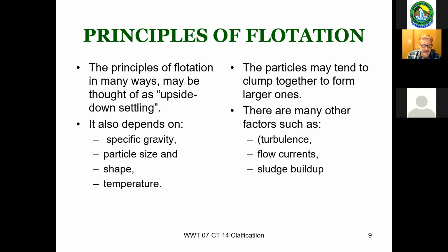Flotation depends on specific gravity. Obviously, if something's heavier, it's not going to float. Particle size and shape matter as well. If you can slow things down, some of these particles tend to clump together, and then they'll rise to the top. In the primary clarifiers, you definitely don't want a lot of turbulence. If you are experiencing turbulence in your primary clarifiers, hopefully you have another clarifier that you can add into service.